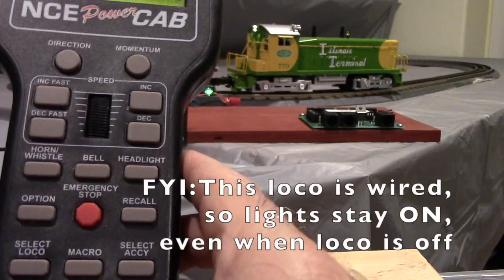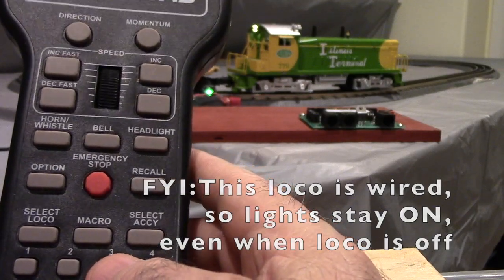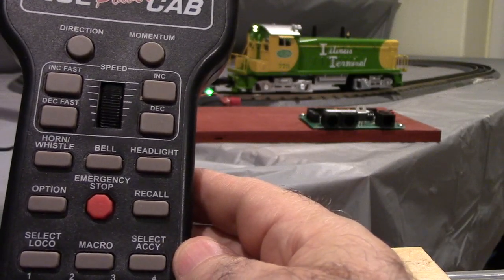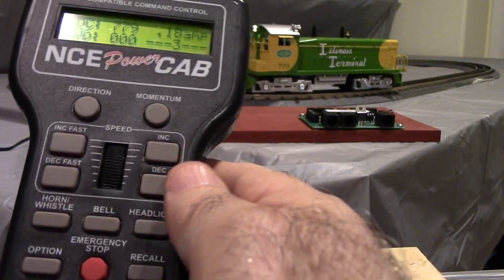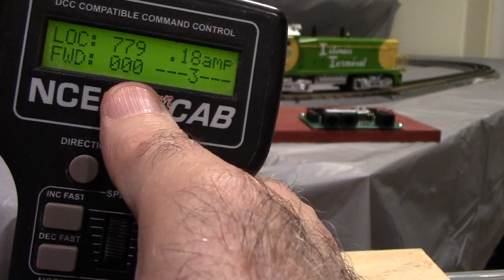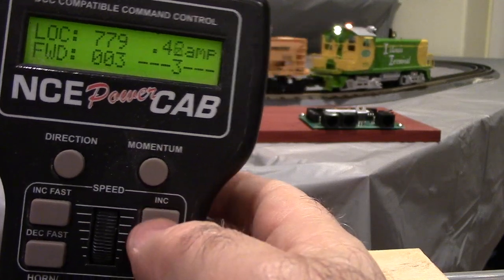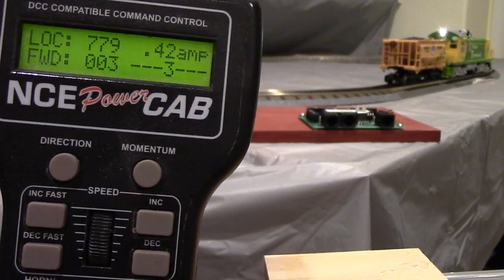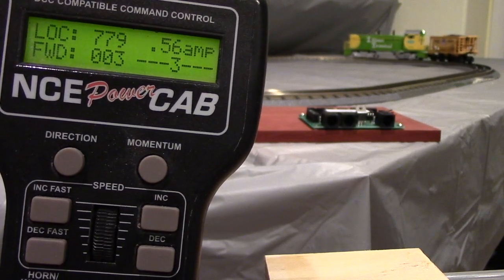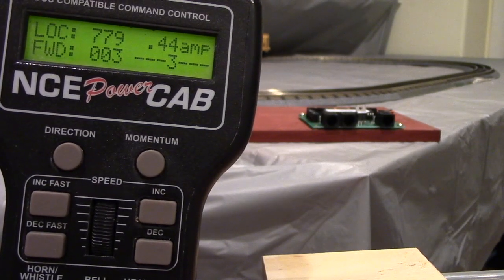To turn this loco on, we'll use the function 3 key, which is where I've got my thumb here. So if I push that 3 key, you can hear that loco is powering on. And we're going to set it to speed step 3, and I'll use the increase button here. You can see on the lower left of the display it says speed 0. We'll increase that to 3. So now we're running our locomotive manually at speed step 3, and you can see it's pulling about a half an amp, so we're well below our 2 amp maximum. So what we want to do now, let's stop this loco.